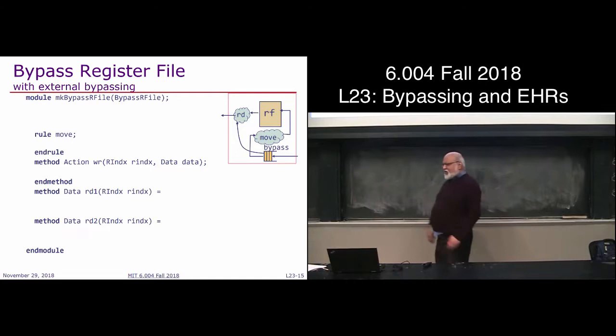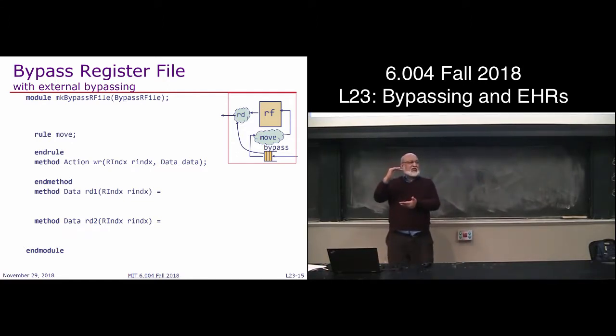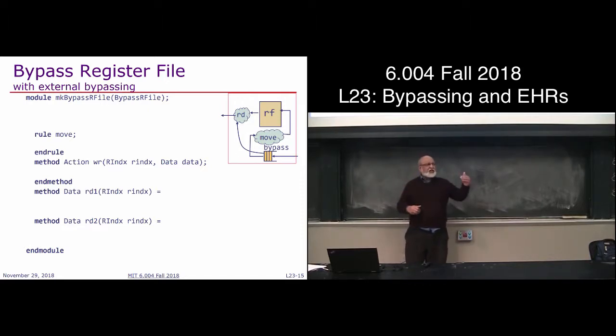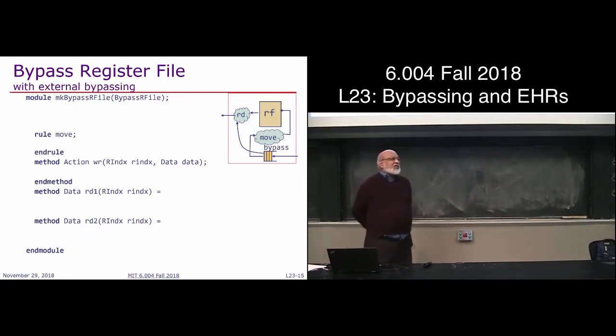So I have my ordinary register file which keeps old values, right? But every time you do a write, I create a small buffer here. So new values are being written here, because I may not have had time just to go and update the register file. So whenever you do a read, before reading the register file, I just read this buffer first. Say, is there a value for register R in here? Yes, then I read that one. If not, then I go and read the register file. So that's the whole idea that is trying to be captured in that diagram that is shown up there, where RF is the ordinary register file and this whole blob will behave like a bypassed register file.